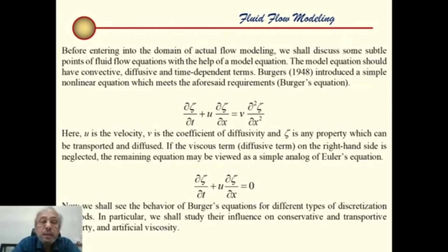You can see we have written the equation where u is the velocity and nu is the coefficient of diffusivity or viscosity in case of modeling fluid flow problems, and zeta is the property that can be convected and diffused, and this is the temporal term.